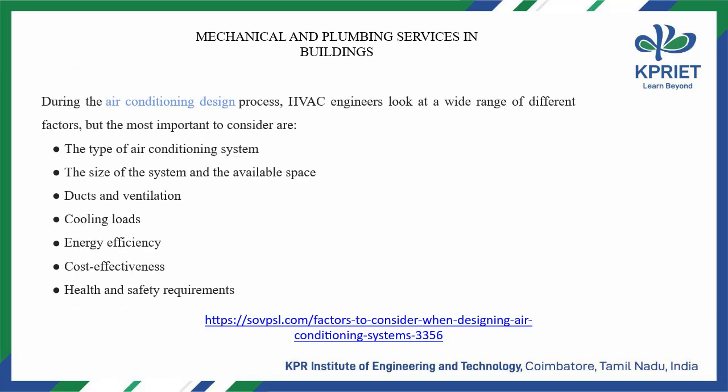During the air conditioning design process, HVAC engineers look at a wide range of different factors, but the most important to consider are the type of air conditioning system, the size of the system and the available space, ducts and ventilation, cooling loads, energy efficiency, cost effectiveness, health and safety requirements.